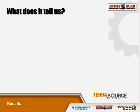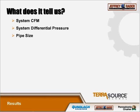So what does that tell us? System CFM is going to be important for our calculations. The differential pressure is also going to be very important. Pipe size, obviously. Size of the cyclone required, the blower size, and the feeder size. Now, all these components are selected based on that given set of criteria and are unique to that criteria.